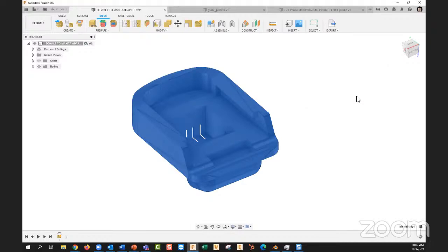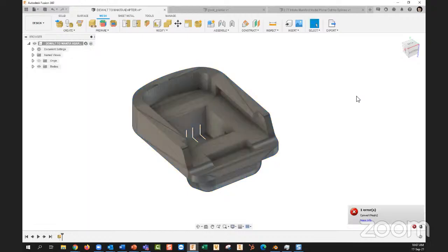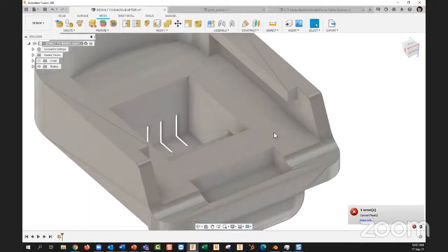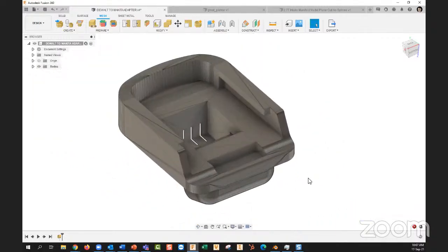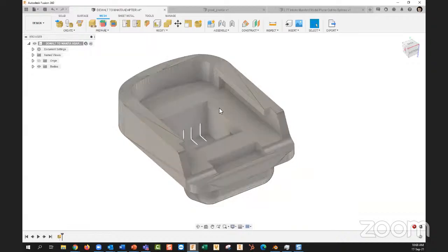I'm going to go ahead and try to hit OK here, and we're going to see an error because we didn't follow the formalities of this workflow. So essentially, it's trying to calculate the meshes and is trying to see that this is one flat face, but we didn't line it up to be successful by giving it what is called this new tool called face groups. Now, face groups automatically defines what each face is a part of, what group it is.